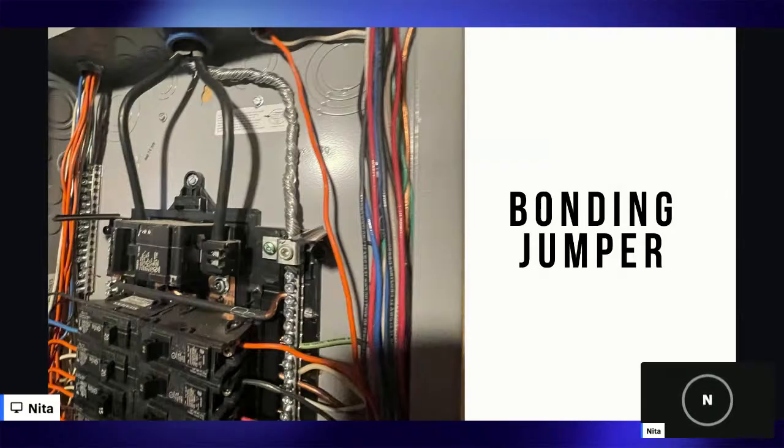If you are inspecting a lot of newer homes, you likely will see some sub panels. A sub panel is basically just another ancillary panel to serve an area of the home. It is downstream from the main. So in those panels, neutrals and grounds need to be isolated. In the main panel, they're connected or they can terminate on the same bus bar. We're going to talk about bonding in a second. But the bonding jumper is just the metal strap.